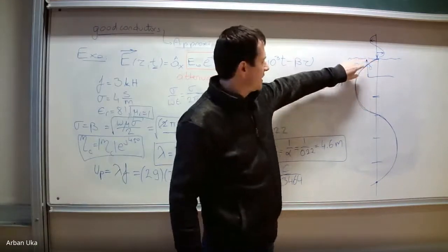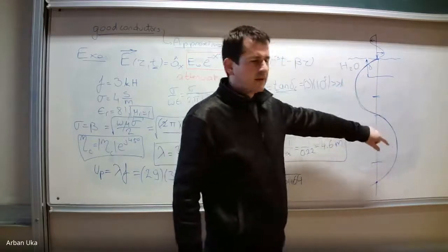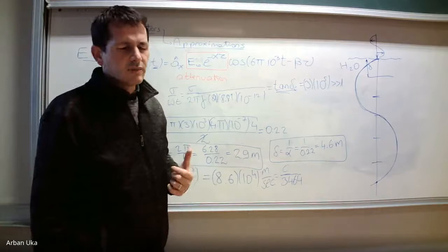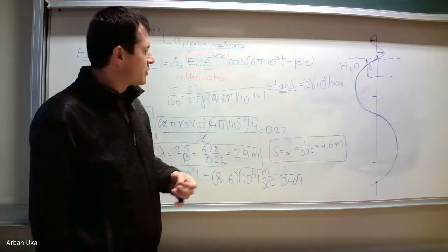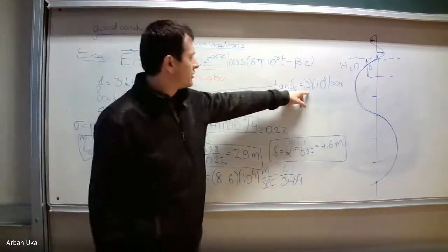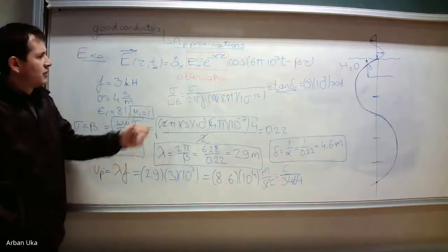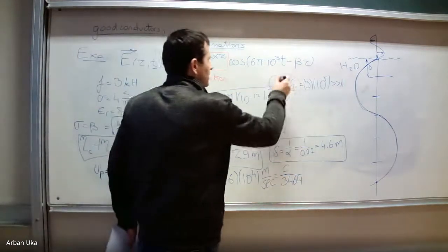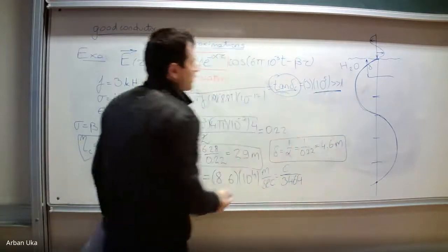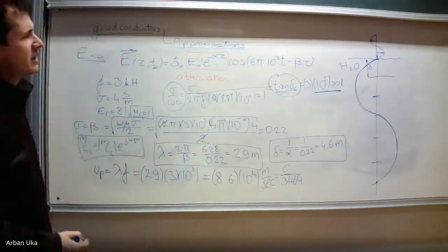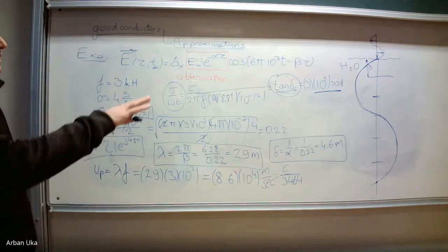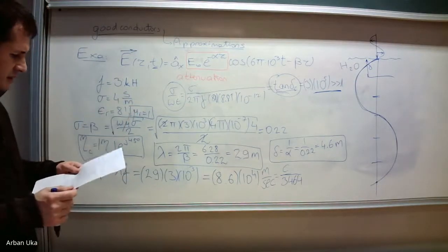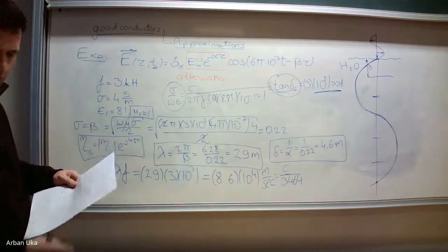So before completing its complete wavelength, the wave is attenuated considerably, and this is because we are dealing with a very good conductor. If you look at these numbers for the loss tangent, either this or this, these are all on the order of 10 to the power 5, and that's why we have this configuration. But it should be good to understand how we understand that figure.